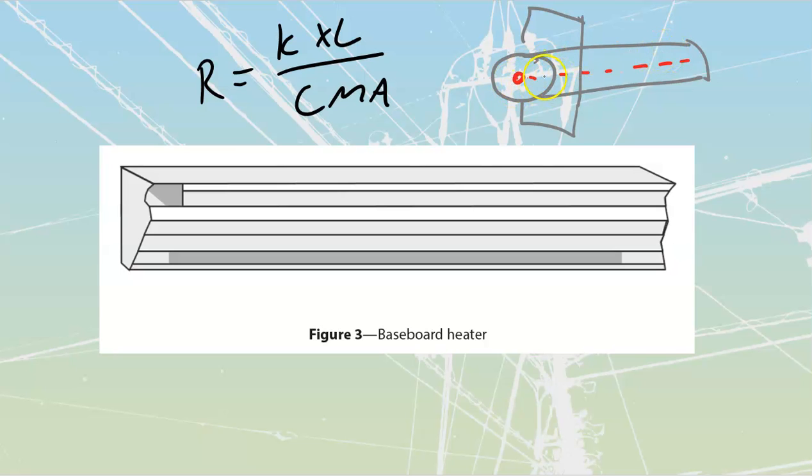So the ceramic tube has got the nichrome wire inside. The nichrome wire is going to have a fairly high amount of resistance to it, and we are going to be able to dissipate a lot of heat off it. We carry the heat from the nichrome through the ceramic, which isn't awesome, but we need it for the insulation and for the support, and then out to these actual fins, and then these fins will radiate that to the air itself.